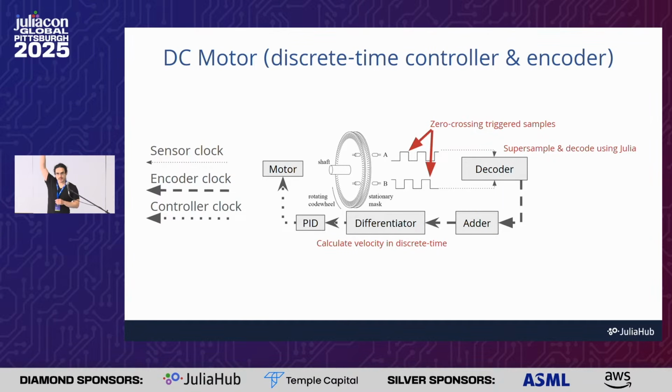There's two signals coming off of the encoder. There are 2 sensors on the encoder that are giving us sort of chopper signals. I'll show you this in a second. They're then being mixed together and decoded to tell us how far the wheel has actually spun.